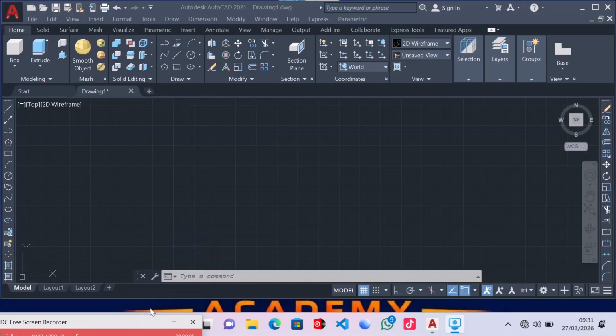Basically, we look at the side of beginners who have just opened up AutoCAD and have an interest in learning AutoCAD. So now, when you open up AutoCAD, these are the few things you need to know before doing anything. First of all, you need to set the page. Second, you need to learn how to use a few toolbars for you to have a simple drawing in AutoCAD.